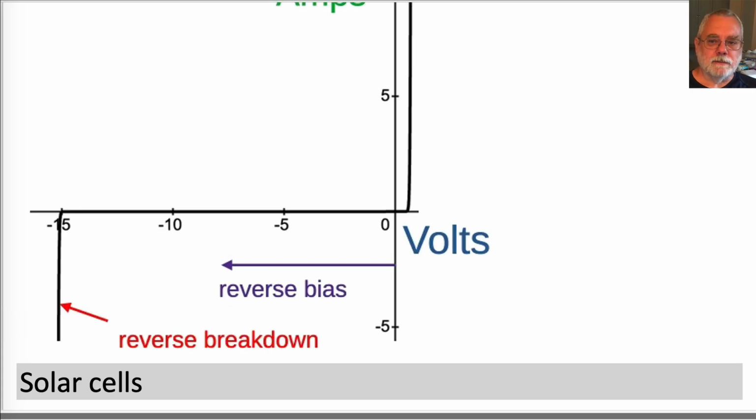Now let's look at solar cells. A photon of visible or ultraviolet sunlight gets absorbed in the junction depletion region and creates an electron-hole pair. The mobile carriers drift to their respective majority regions. Under the right circumstances, the solar cell supplies power to an external load, say 5 watts or more per solar cell in ideal conditions for modern solar panels.